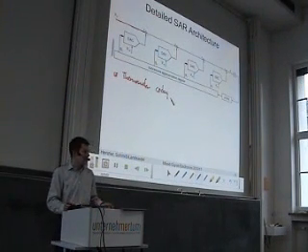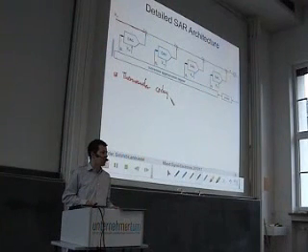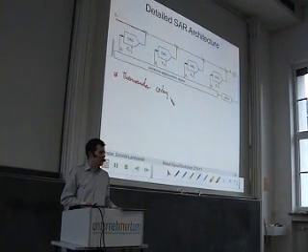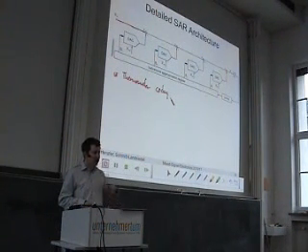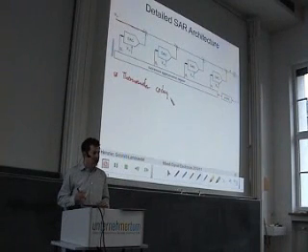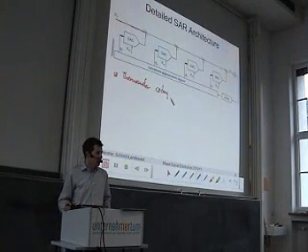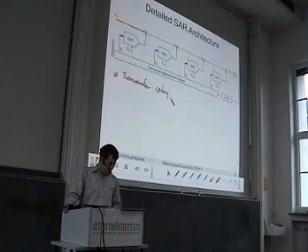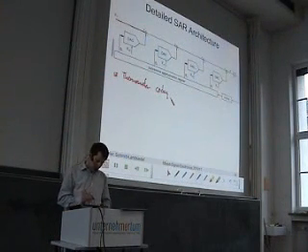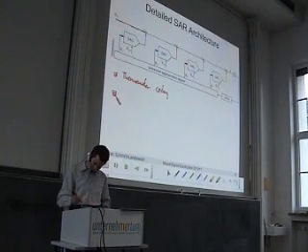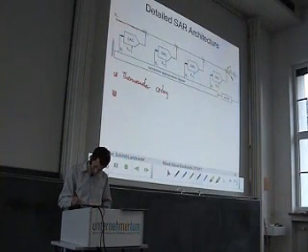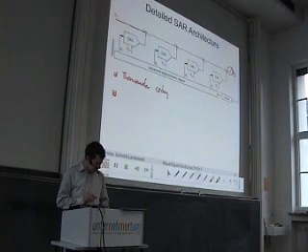And what was the main disadvantage of thermometer coding? Well, it is for sure the effort, because for each step we need another element. However, the advantage was it is strictly monotonic, and we can here compute the remainder, which is this error here, the quantization error.